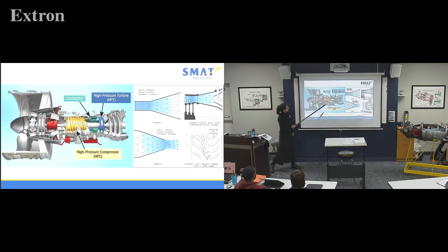So we come right to, it's a little harder on this diagram to see what's happening in here, but at the end of the compressor, what is that component? Diffuser. And what does it do to the air? Increasing pressure. Yes, it's not getting compressed anymore because that's ended over here, but it is increasing pressure.